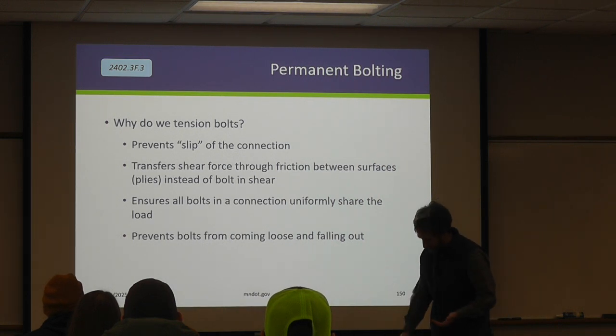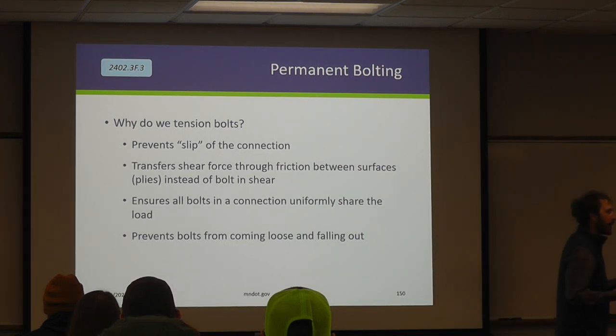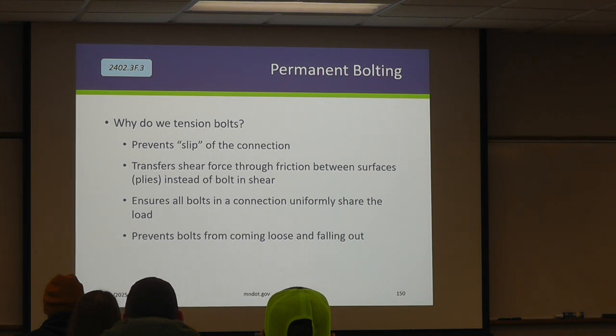We also want to make sure that through the tensioning process, all the bolts are carrying about the same load. So if you have a couple loose ones and a couple tight ones, you think that load's going to be distributed nice and uniformly? No, load always wants to go to the stiffest spot. And then, obviously, to prevent them from coming loose and falling.